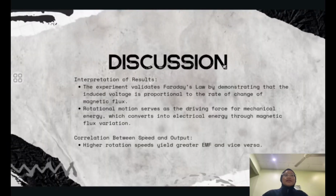What can we discuss from our project? First is the interpretation of the results. So the experiment validates Faraday's law by demonstrating that the induced voltage is proportional to the rate of change of magnetic flux. Second, the rotational motion serves as the driving force for mechanical energy, which converts into electrical energy through magnetic flux variation. So the correlation between the speed and the output is: the higher the rotation speed, the greater the electromotive force, and vice versa.